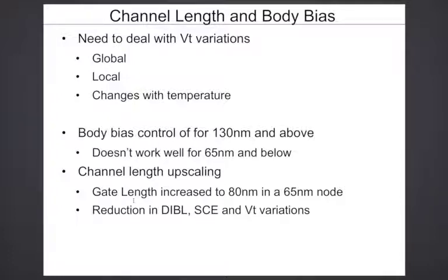Now, doping is something which happens one time during the fabrication process. But as a designer, you have a choice as to which threshold voltage to choose, right? Because any process now comes with transistors with multiple different threshold voltages. So it's one time, during design time, you identify what is the threshold voltage to use, and then you pick that in your design. But once you make the design, then you have also another choice, which is the sizing. Based on the sizing, you can also control the threshold voltage.